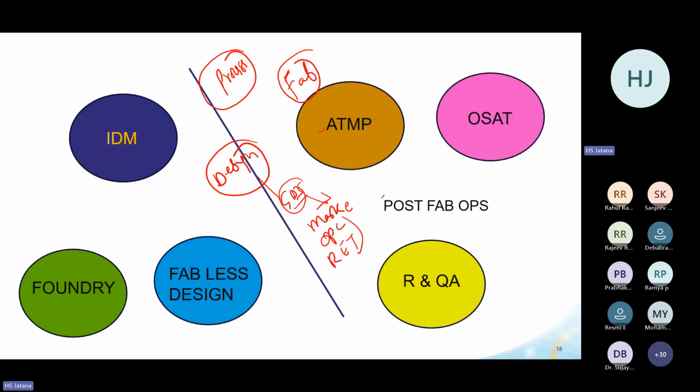So they will change those GDS data, and they will make the mask. That mask set will go to the fab, and the fab will use those mask sets and all the information given by the process in terms of the batch flow, unit processes, and things like that. They will run those batches, and it is the responsibility of the fab people to ensure yield. Yield has to be stabilized. First of all, it has to be close to more than 90%, and it has to be stabilized from batch to batch.